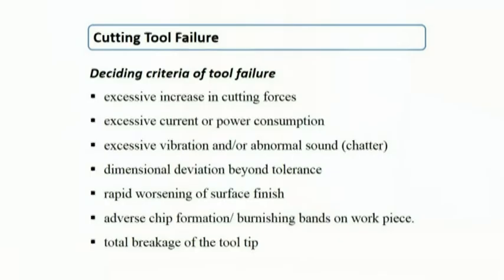Then the surface integrity, surface quality. Initially you are getting a good surface finish, but after some time, due to the wearing, due to the failure of your tool, you are not getting the surface finish as required. Your machined surface is observed poor. So that also indicates that there is some kind of failure in your tool.